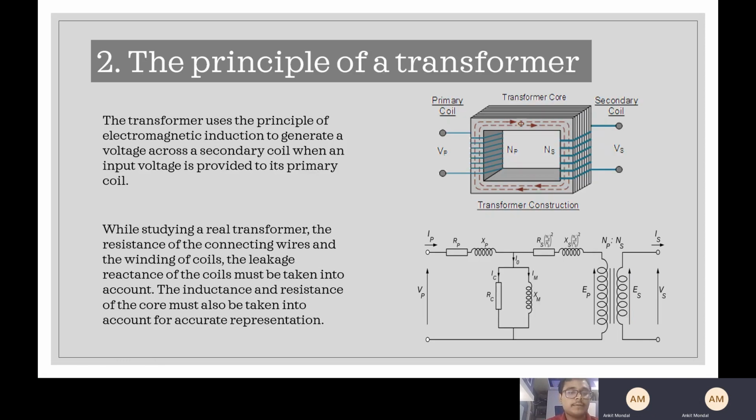Well, we have seen in our lab classes how a transformer works, how it can be used to step down voltages. We know the relation that Vp by Vs is equal to Np by Ns. And this is an equivalent circuit of the transformer. These are the impedances referred to the high voltage side and can be calculated using the various tests that we saw in the lab test.